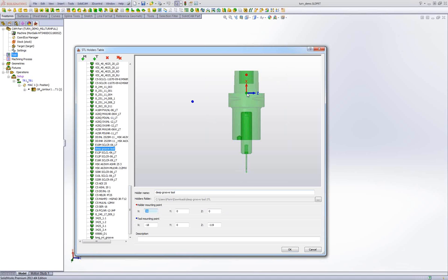If the export is not with the coordinate system, when you do export is not in the correct place, maybe you have the coordinate system here and you want to mount the tool with the center, so you just shift in the red dot. Now is in correct place, so X, Y, Z will be 0.